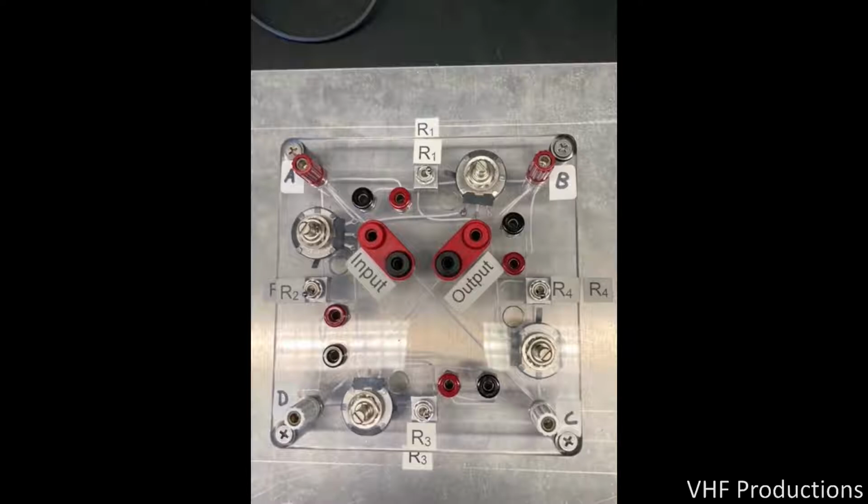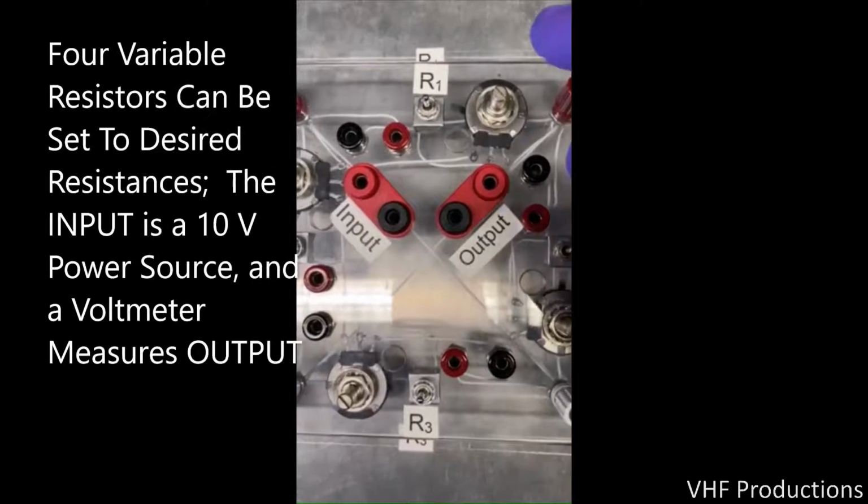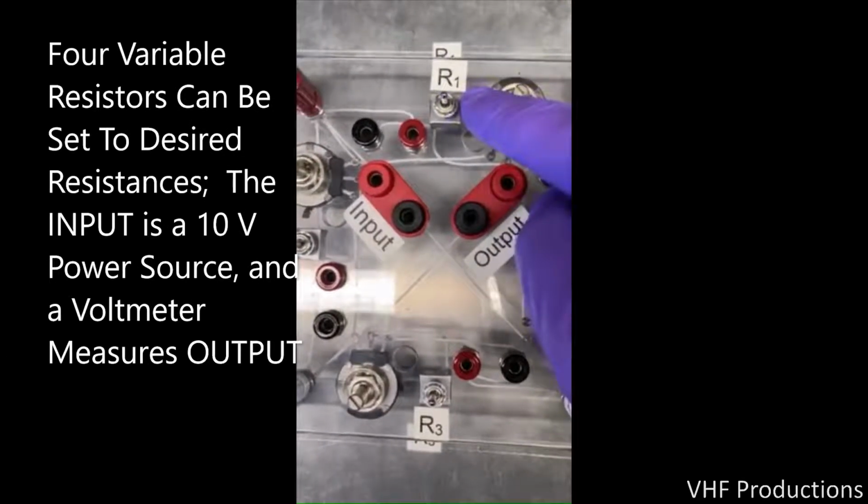When it's switched to the middle position, there's a short between pins B and C, and when it's switched all the way up, it puts the connector pins red and black, which would have, for example, a strain gauge plugged into it, puts that strain gauge then into the resistance path. And that approach continues along the bottom and again along the left side of the resistance paths R3 and R2.